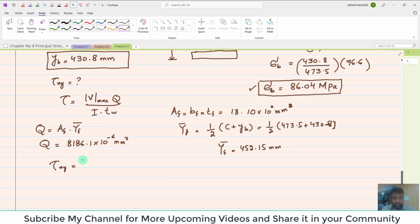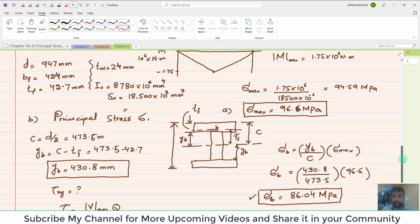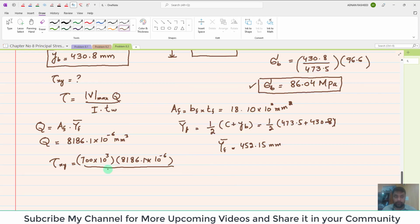So 700 into 10 raised to power 3, clear, multiplied by this Q, which is equal to 8186.1 into 10 raised to power minus 6, clear, divided by I of the beam, which is given over here, that is 8780 into 10 raised to power minus 6 meter 4, into thickness of web, which is 24 millimeter.